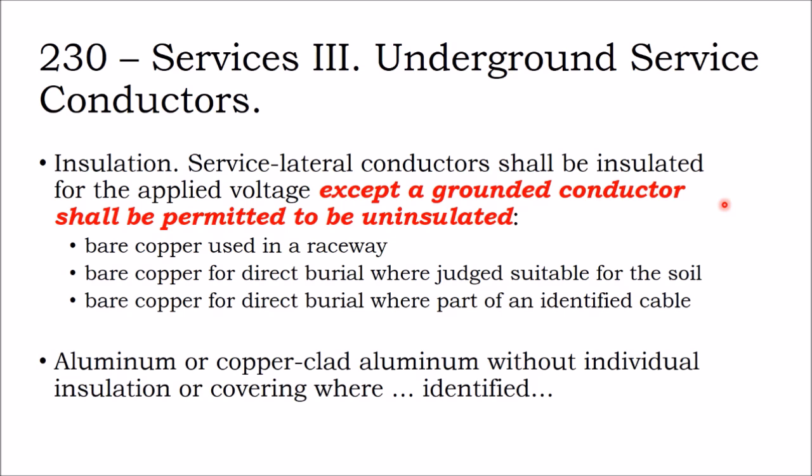But then there's that green ground cable, that equipment ground conductor that's grounding all your metal parts together throughout the installation. And they say, well, that does not need to be insulated. So some installers like to show off and get a green insulated wire with the ground in it. And that's fine too. Good labeling, I will not speak ill of. That's awesome. But it's often permitted for bare copper to be that grounding conductor and not required to be insulated. But a word of caution, bare copper is not suitable for all soil.